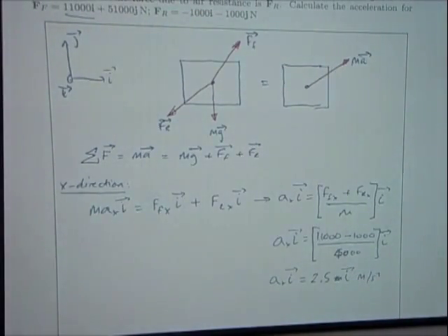So there's the horizontal component of the acceleration. So we know that if we've got our ma there, in the kinetic diagram, we know it's going to be in some arbitrary direction. But we know that the horizontal component of that vector is going to be 2.5 meters per second squared, okay?